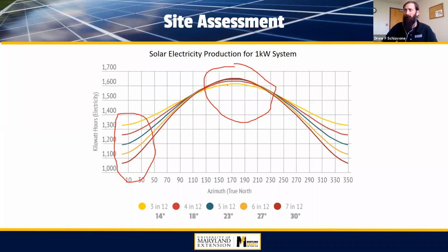If you look at the yellow line at the bottom, if you can see that level of detail on this graph, you do have a little bit of efficiency drop because the angle is so low. And again, with the extreme case, if the panel just falls flat on the ground and it's pointed up, it's not going to be as efficient. So you want to stand it up and match the latitude a little bit better, but there's not going to be a huge difference between 39, 40, and even maybe 45 and 50 degrees. You can deviate from that a little bit.